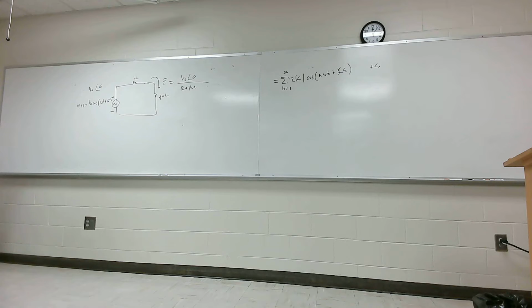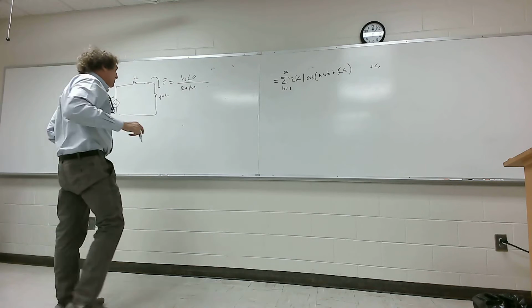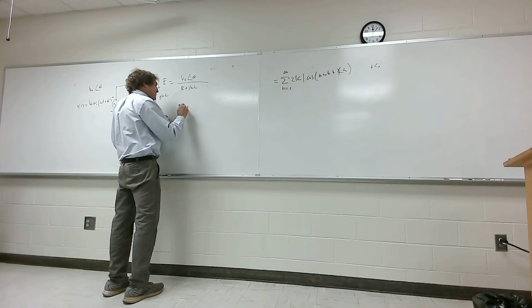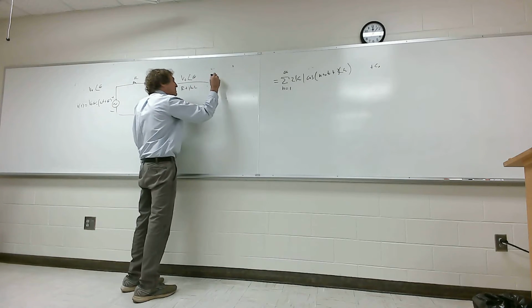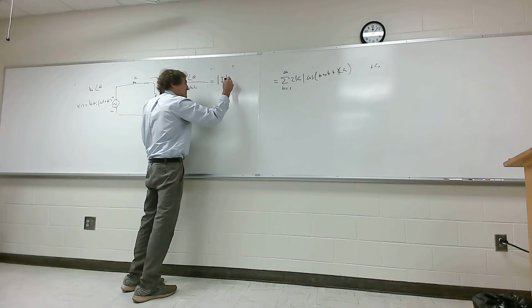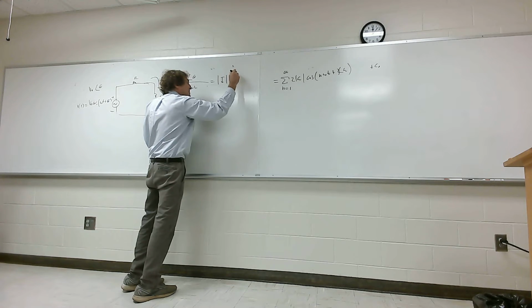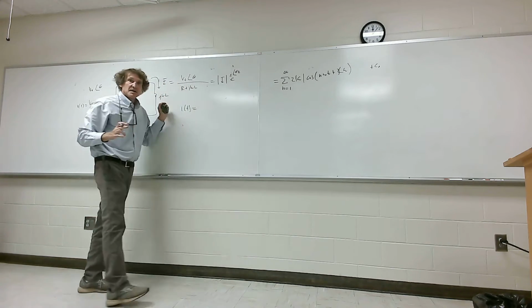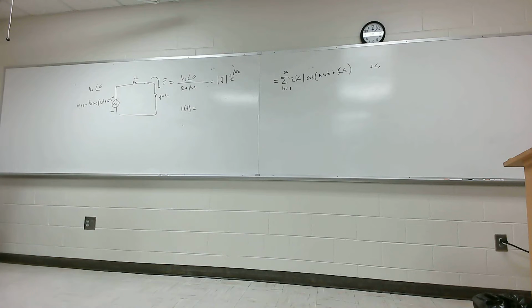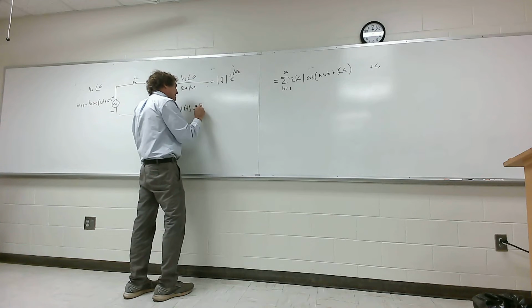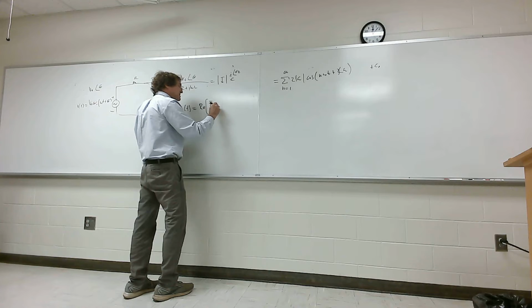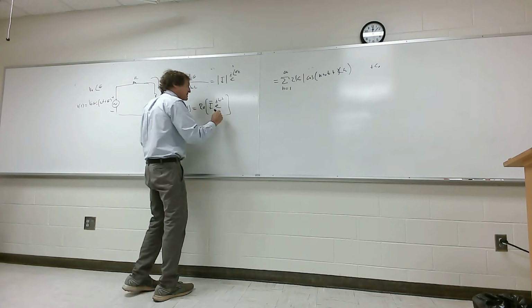Once I get that, how do I get the time domain form? Well, remember, this is really what? It's some magnitude of I, right, at some angle of theta I. Isn't it, class? With me? Now, how do I get i of t? Remember this. It's the real part of the phasor times e to the j omega t. That's all it is.